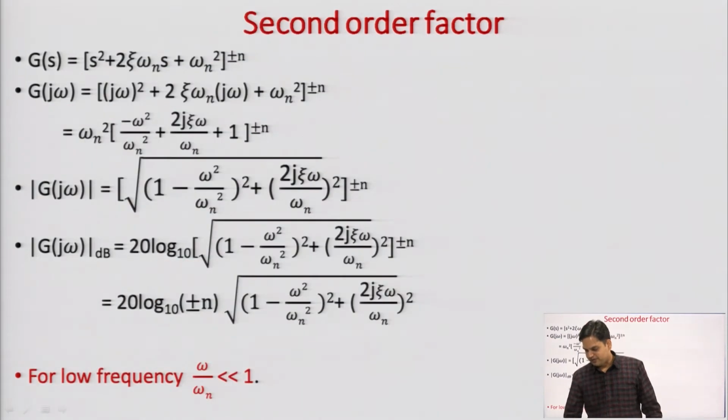So, always remember, whenever we are designing a system, say an analog filter, I would like to know how many poles are present. Then I have to see my phase plot and the change in phase. If the change in phase is 90, it means a single pole is present. If the change in phase is 180, it means 2 poles are present in the system.